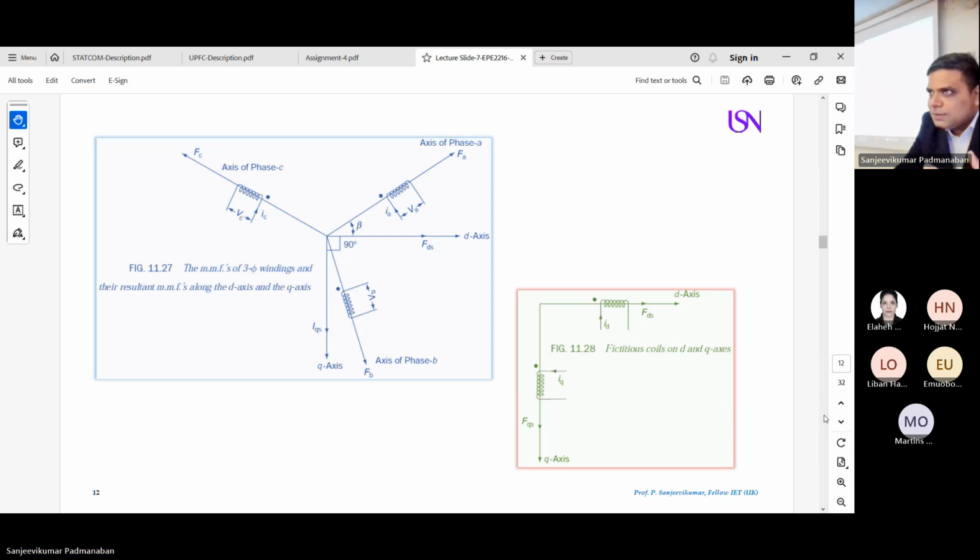If you have seen my previous lectures on power system analysis and power quality, I have given all these details. If there is a small change in the three impedances of your system, your voltage will not be balanced. There will be a small difference in the voltage. For example, 400 volt line to line: one will be 399, another will be 400, the third one will be 394 or something. I give an example. So this unbalance will come if you have a zero sequence component.